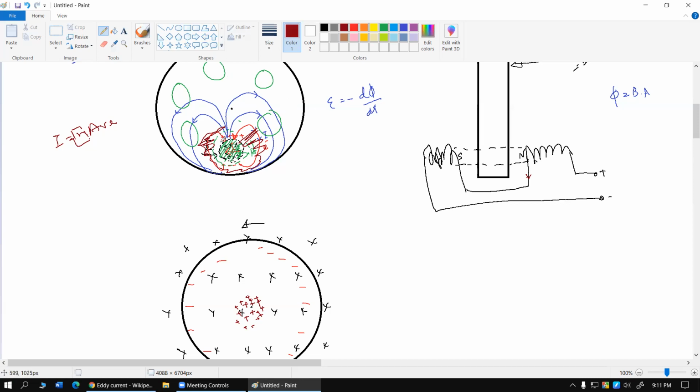And as the vehicle slowly starts to decelerate, it has a lower speed, so the rotational speed of this disc becomes less and less. They can slowly increase the current on this disc to maintain uniform deceleration. The bottom line is that when the disc is moving fast, you introduce a small magnetic field to produce a fixed amount of slowing, or a fixed amount of kinetic energy into heat energy conversion.